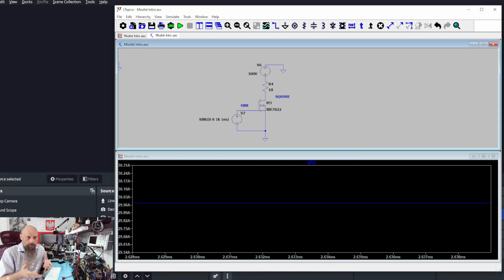The MOSFET is designed to work as a switch, which means in bipolar transistor we can use this range where transistor semi-opens, semi-closes, which causes a lot of power to dissipate on the transistor. But we can use that linear property of the transistor for amplification, for processing signals. We can use it for a lot of things. But MOSFET is designed to be just a switch.